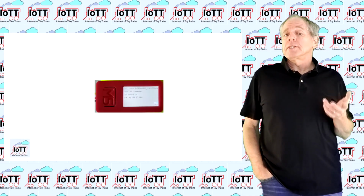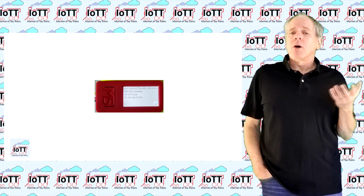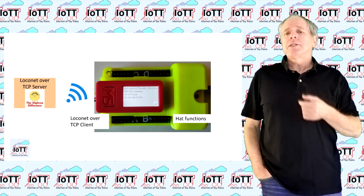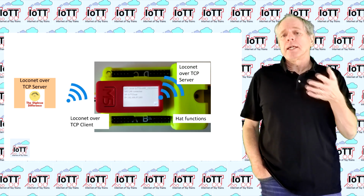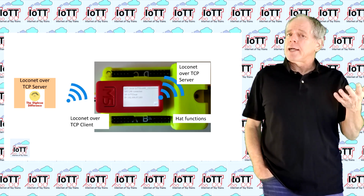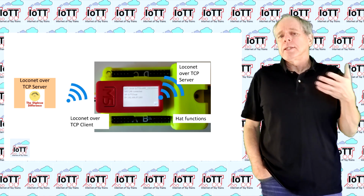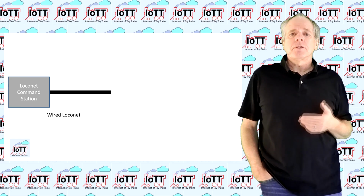On the IoTT Stick, Loconet over TCP works the same way. The stick can operate as a client connecting to an upstream server, and it can provide a server for other clients to hook into. It is even possible to have both on the same stick at the same time, so getting the Loconet messages as client from a server, and then provide a Loconet over TCP server so that other programs or IoTT sticks can hook into. Here are some examples of what you can do.